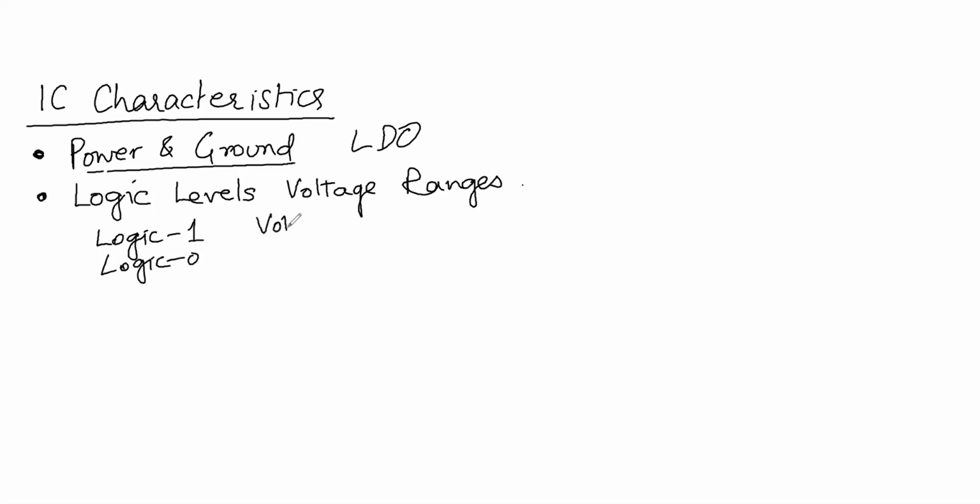Either it has to be a voltage, or it has to be current. These are the two basic physical quantities which you can apply. MOSFETs are typically voltage controlled devices, BJTs are current controlled devices, but still the input output voltages are important even in BJT, the current mode devices.